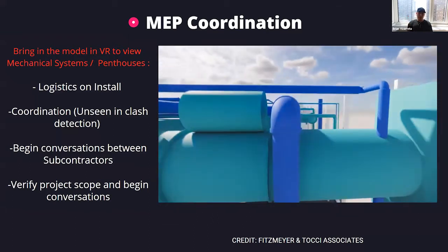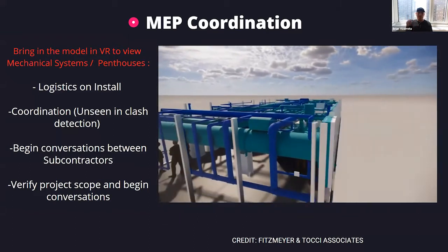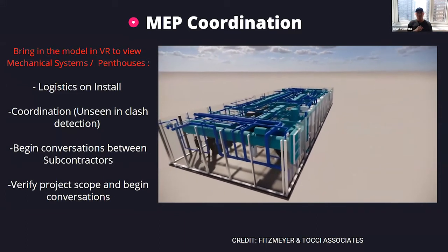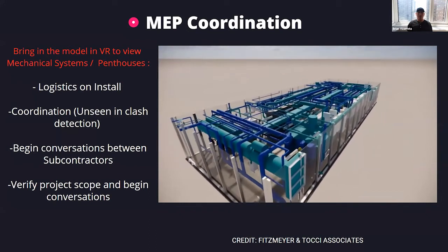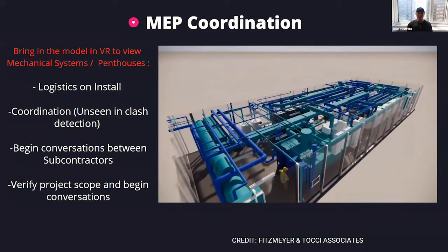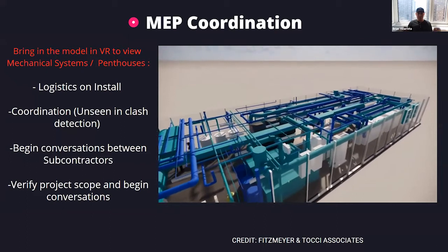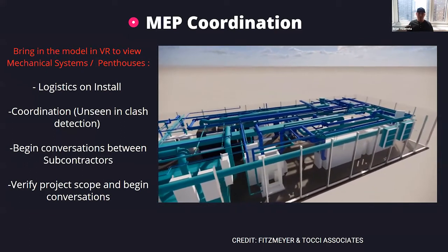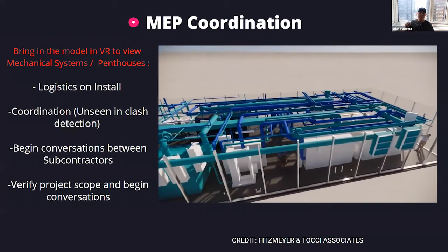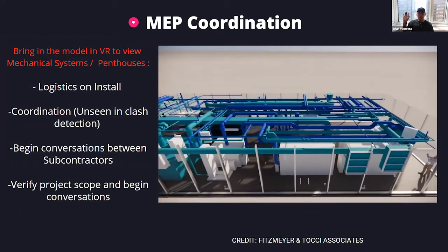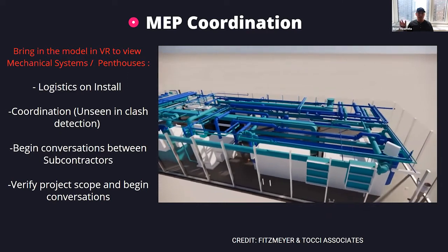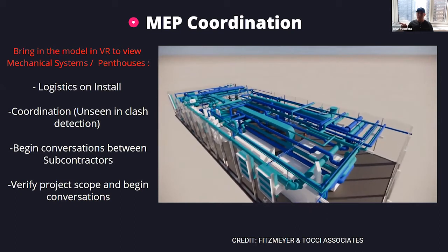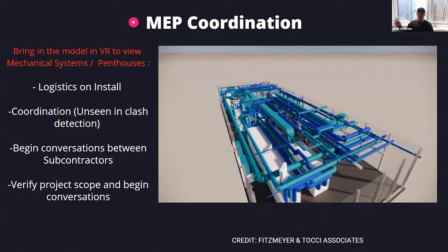So there are times where, yes, you may not have a clash per se, but something may not be feasible, such as how is the facility manager going to get in there and turn off this valve? Right. So technically, yes, you may have your clearance around this box, 3 feet, etc. But if you can't even get into the space very easily, for example, it's like an emergency shut off, then later on down the line, they're going to realize, hey, that's not really accessible. I need you to add a couple more shutoffs here and there.